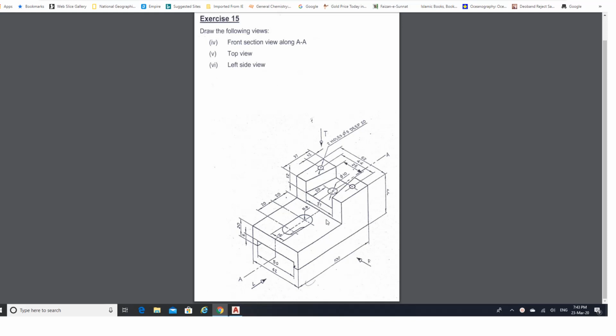So what shall we do now? Let's first decide how to go ahead with this job. This complete portion we will make separately first. Then we will create this portion and the center portion, and add all of them together. Finally we will create one small rectangular cube and subtract it from the whole thing. That will do our job.